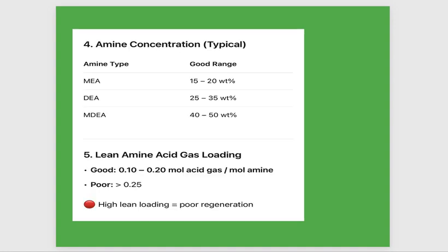Look at the amine concentration, as we mentioned before, and we mentioned what can lead to loss in the concentration of the amine, like degradation, like passing from the PSV, like skipping or carry over with the acid gas. Many items can lead to loss of the concentration.